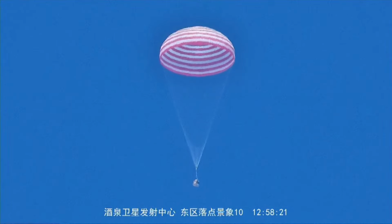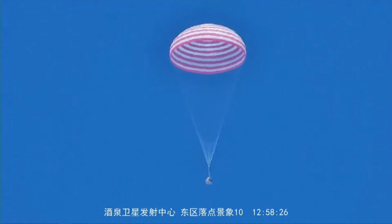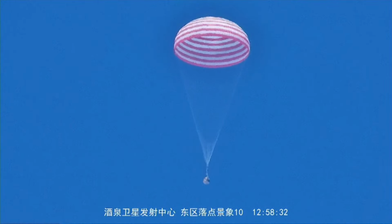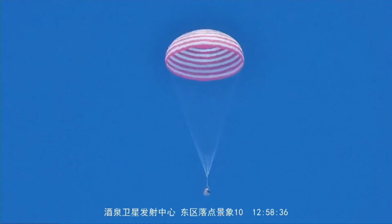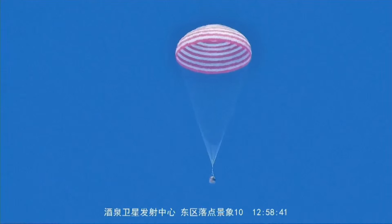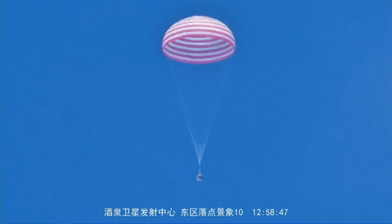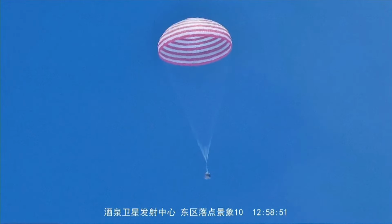And you know that even with this huge parachute, it's still too fast at touchdown. That is the reason why we need 4 retro rockets. When the distance between the vehicle and the ground is about 1 meter, we will ignite the 4 rocket engines, and the speed of the vehicle will slow down to less than 2 meters per second. Can the control be that precise, just 1 meter above with this 3-ton payload, when the ignition will happen?